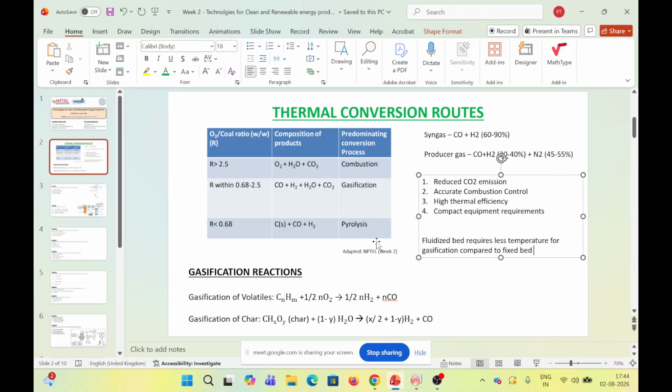Usually for this we use a two-stage water wash process wherein you wash the syngas with a quench pipe and a packed tower. Using the quench pipe, 95% of the carbon gets removed, and in the scrubber you use a circulating system to remove the particulate matters from the syngas.